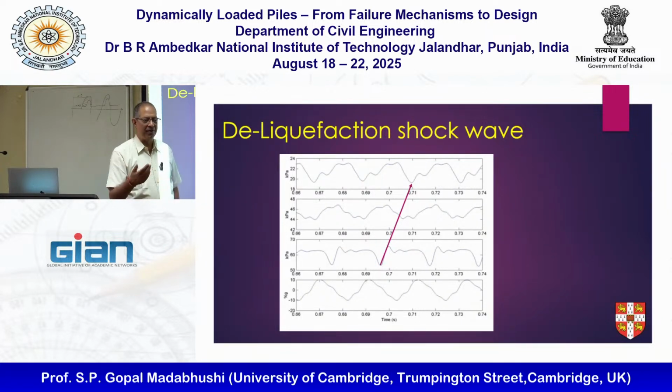Like if I know P wave velocity, I can tell you degree of saturation and all kinds of other things. Skempton's B parameter and other soil mechanics related stuff also falls out of this. But the biggest thing here is what Cutter and Balakrishnan said are the deliquefaction shocks. We can observe directly from the data.